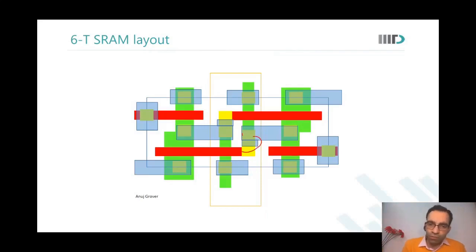Even these notches that you have, the M1 notches that we have shown here, even these notches could be violating DRC. But all this is allowed simply because we want to gain density, and it is technically possible because this is a very repetitive structure extending over hundreds of thousands of microns. So we can do something about the optical proximity correction over there. If this was not such a broad and widely used symmetrical structure, one would not want to do it. It's much riskier.